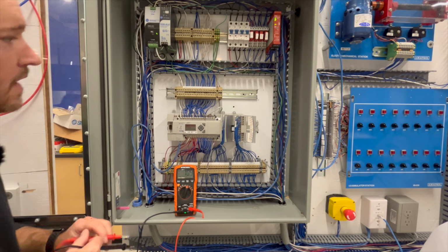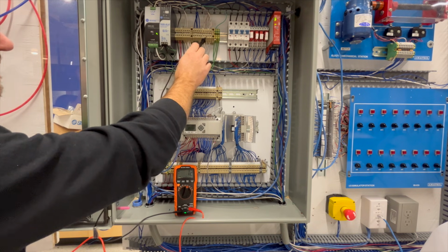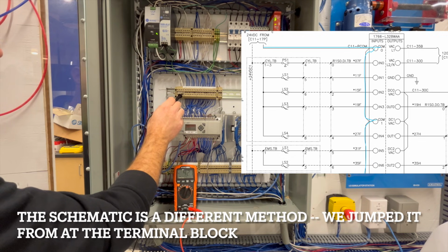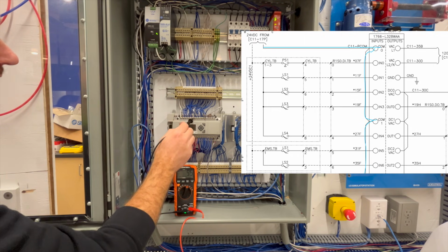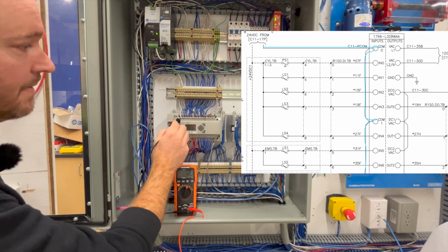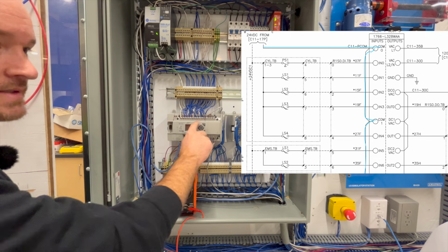So then I want to come to these jumpers. How this was wired is 24 volts came in from this terminal block here. It's run down and jumped to here, and these four are jumpered together. And then it's individually dropped down to all four of these. With some PLCs, you will see just one common come to here, and then that common is just jumped to each common that is on this list right here.